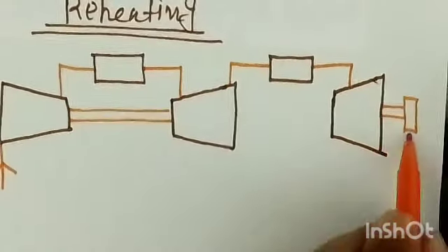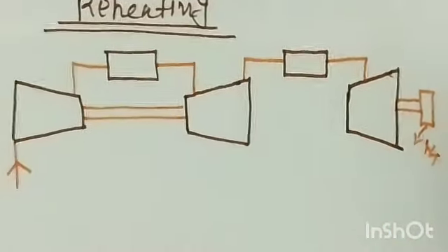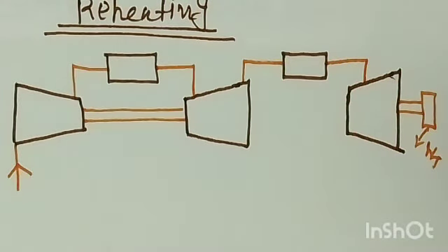The expansion will take place and the work has developed, right. So this work is your work output, or the low pressure turbine work is also known as the power output, right. So whenever you have to find out the power output of a cycle in a reheating case, the power output of a cycle is nothing but the work developed by the low pressure turbine, that's all.